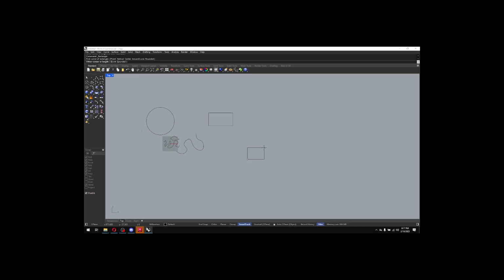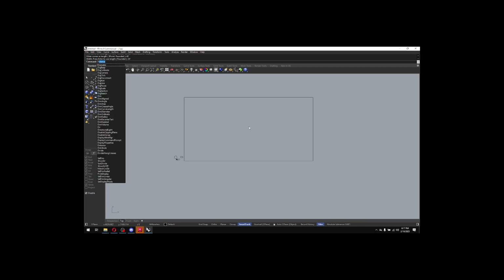So if I need a rectangle that's 40 feet by 20, I would click my first corner point, type 40 feet. Oh, we've been drawing very small. And then to get my other direction, I would push my mouse in the direction I want it to go, type 20 feet, and now I have an exact size. If I need to double check that, DI for distance.